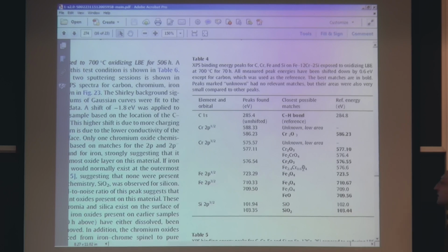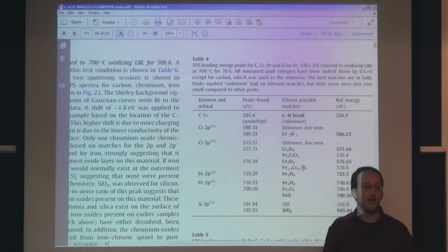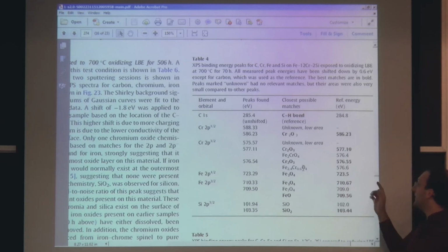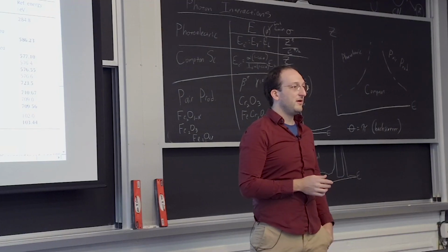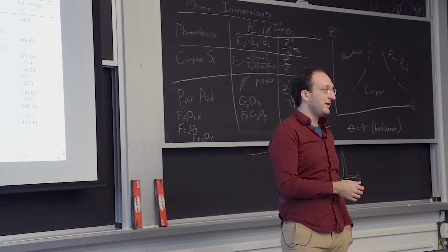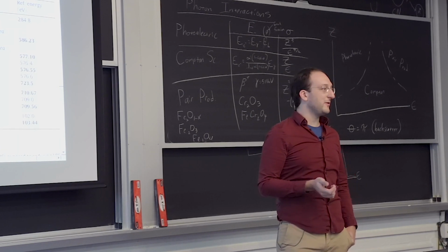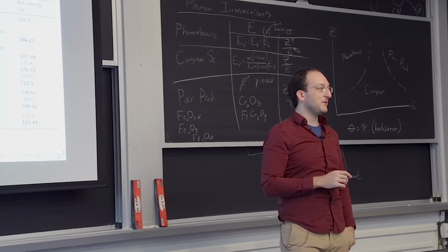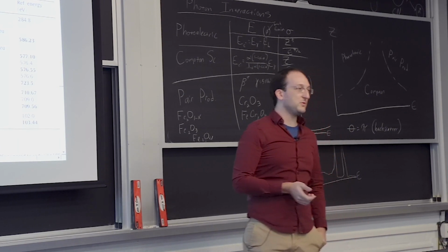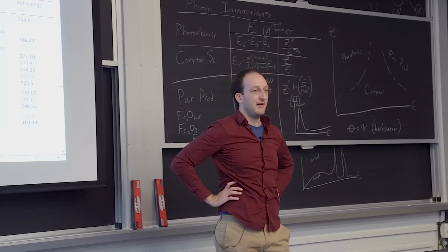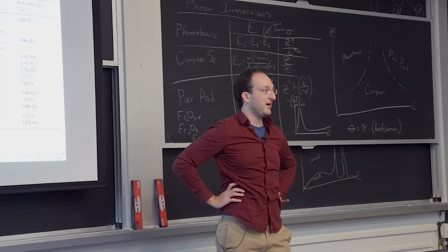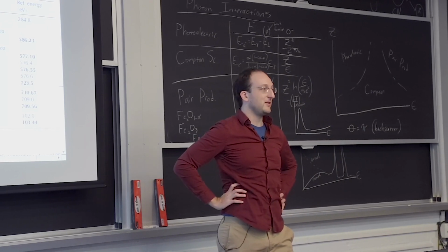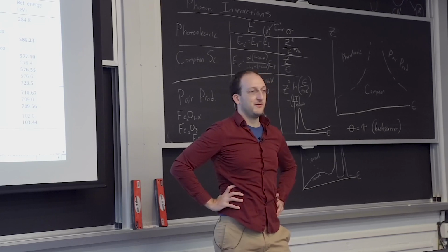So you can look at the peaks to a resolution of about a hundredth of an electron volt, compared to reference values taken on pure compounds and materials, to figure out what actual oxides you have. That can help tell you how protective they are, how fast they're going to grow, and whether they're going to be a problem if you want to use this new stainless steel that we developed in a lead-bismuth reactor. The biggest problem with lead-bismuth reactors is lead corrodes like everything. And so the whole point of my graduate studies was to design an alloy that doesn't corrode in lead and make an alloy composite out of it.